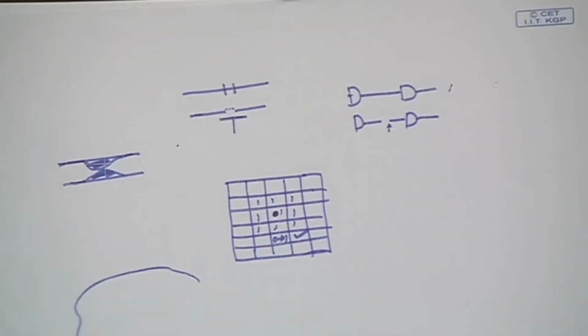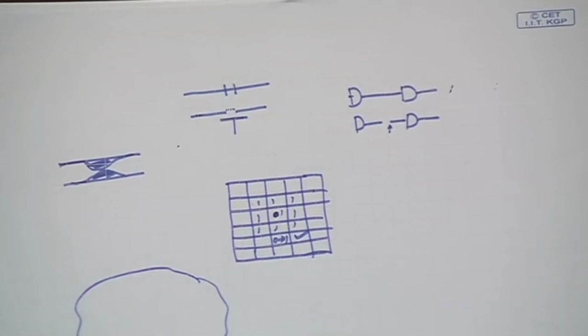Okay. So, it improves controllability in the sense that I can put any desired point in the circuit to a desired logic value. So, that way it is controllability. Similarly, observability means I can observe the value of some point in the circuit by some technique at the primary output. So, what I essentially mean is that if this is the full design that I have now,